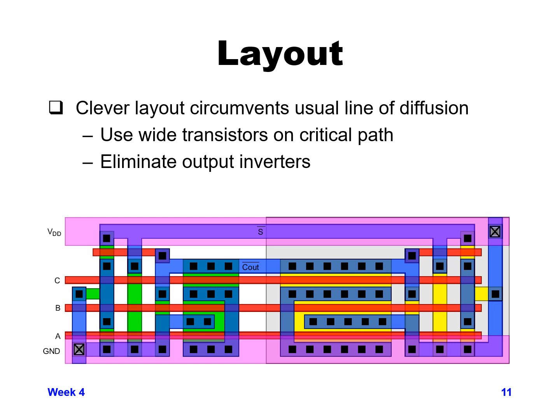If you want to examine this in more detail, it's a little bit easier seeing it in the color version, and that way it's easier to see where the diffusion is versus the gates and the metal. And I think the pink is metal 2, whereas the more bluish is metal 1. So you can use this to examine this particular circuit maybe a little bit easier than the one from the previous slide.